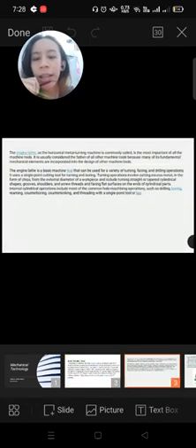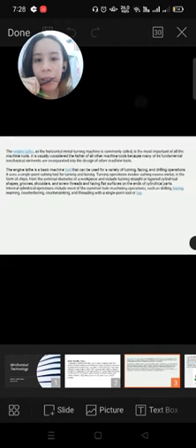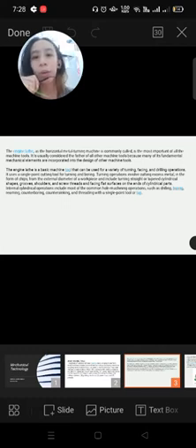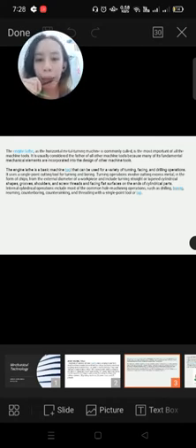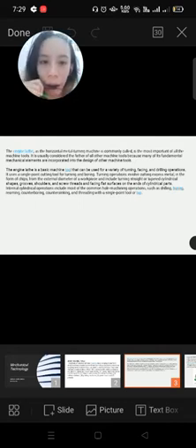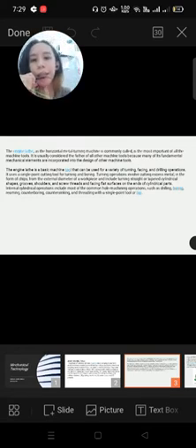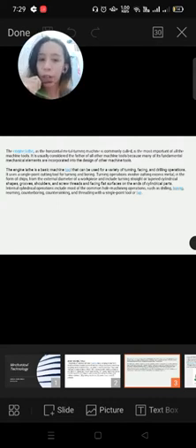The engine lathe, as the horizontal metal turning machine is commonly called, is the most important of all machine tools. It is usually considered the father of all other machines because many of its fundamental mechanical elements are incorporated into the design of other machine tools. The engine lathe is a basic machine tool that can be used for a variety of turning, facing, and drilling operations. It uses a single point cutting tool for turning and boring.